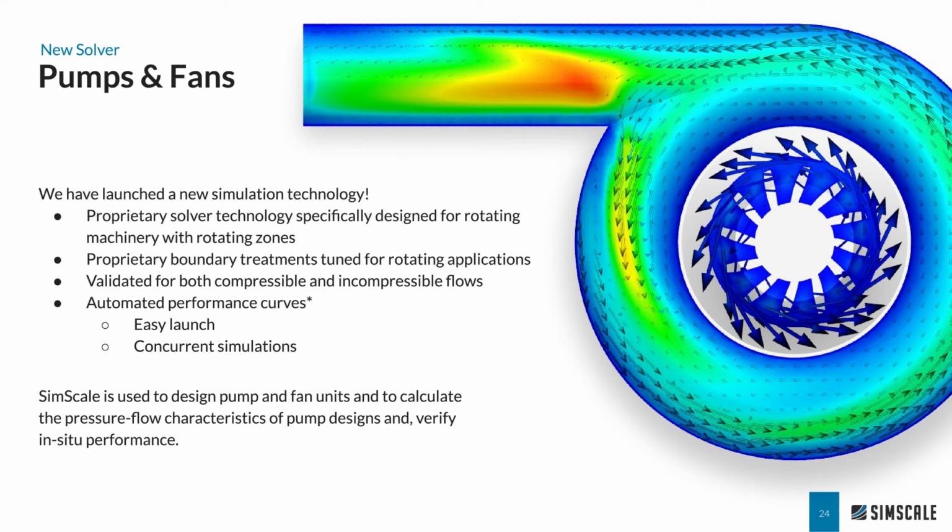You can not only run the analysis of a single operating point of these pumps and turbochargers or the like, but you can also directly run complete performance curves within a click. So this is fully automated to just with a very simple setup get the complete performance curve of your pump or fan design.